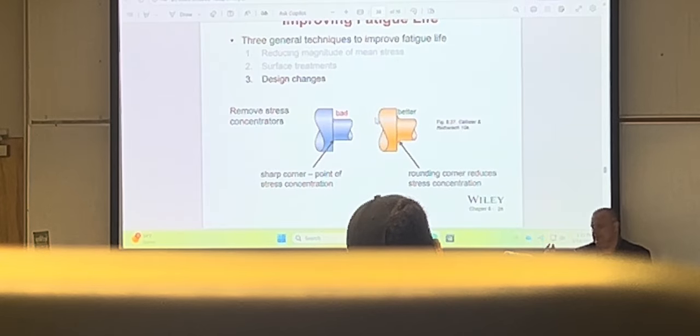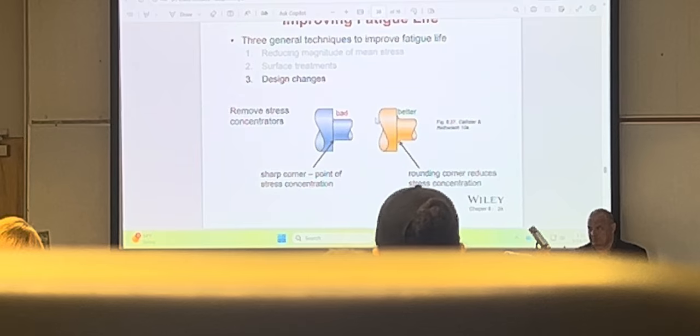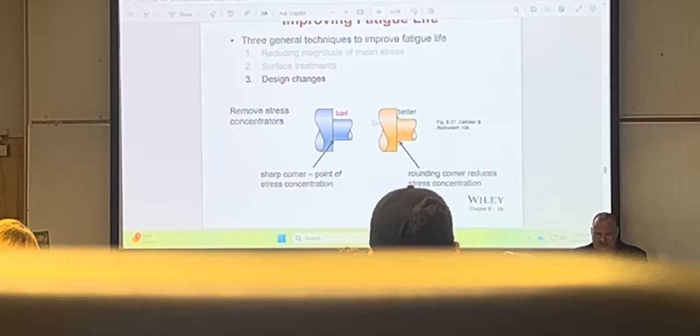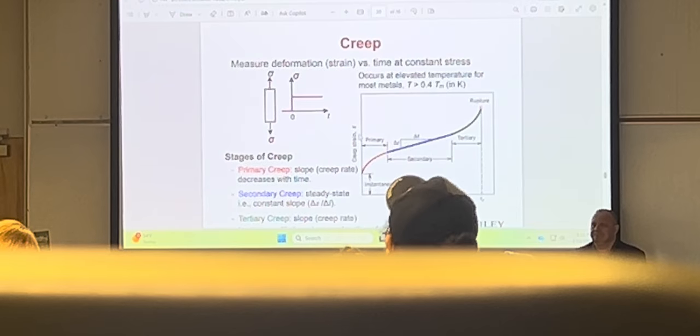Also, external defects, where do they happen? Surface, scratches, mishandling, right? What are the odds of having a defect inside? Pretty small. It has to be a processing error of some sort. But the surface can be scuffed or scratched. The surface itself is already a defect. Any questions about fatigue?